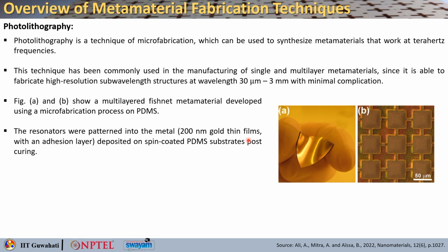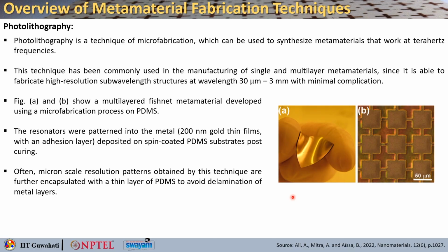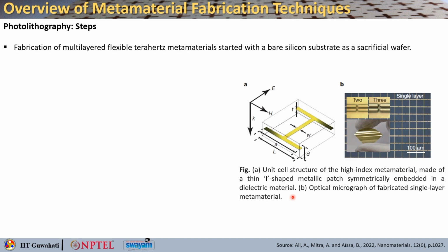So, 200 nanometer gold thin films were used with adhesion layers. They were deposited on spin coated PDMS substrate post curing. Curing is the process of toughening it. Okay. So, often microscale resolution patterns obtained by these techniques are further encapsulated by a thin layer of PDMS to avoid delamination of the metallic layers.